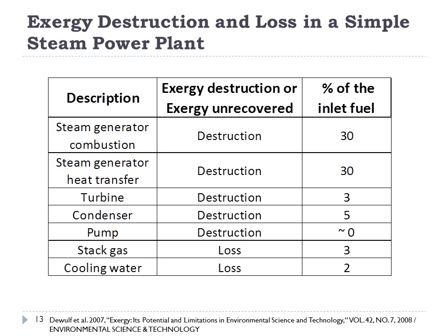The steam turbine has only a small amount of exergy destruction, only about 3%. In the condenser, there's certainly a lot of energy being transferred, but only a very, very small amount of exergy is destroyed, because thermal energy at low temperature has very low exergy. So there isn't much exergy destruction in the condenser, and there's virtually zero exergy destruction in the pump. The pump is just not consuming much power, and liquid pumps typically have very, very low exergy destruction, normalized to the exergy in the fuel.